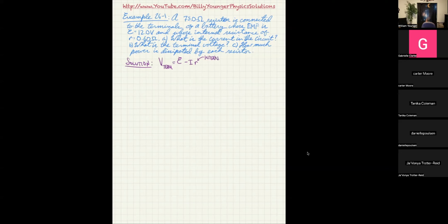So you can see, obviously, if you really want to know the terminal voltage, you have to put it under a load so you can find out what the current is. Or if they tell you that they want a specific terminal voltage and they tell you the EMF, the ideal EMF, then you can use that to decide what current would be necessary. I was saying this is internal resistance.